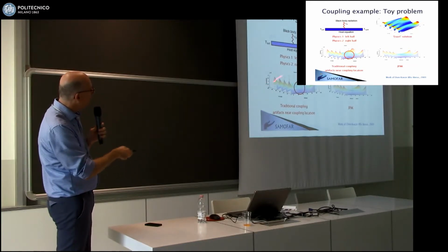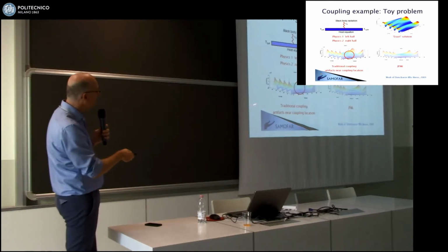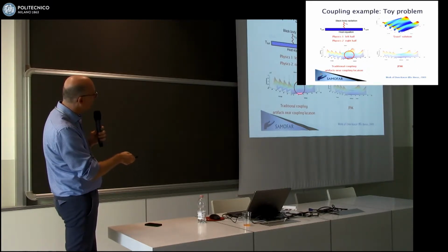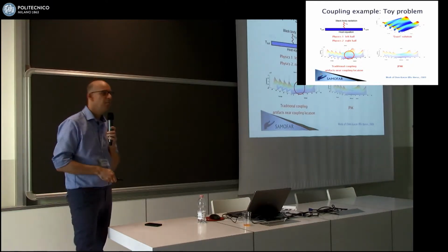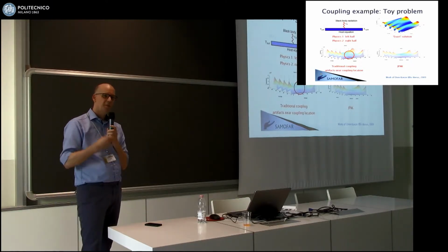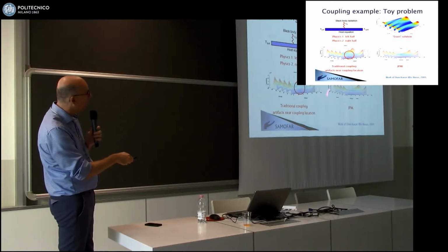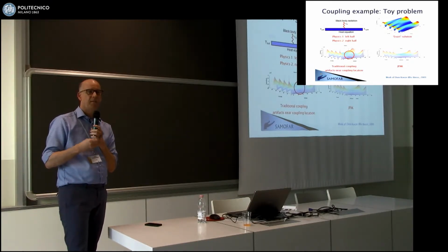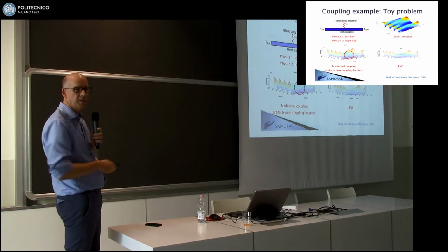And if you then do loose coupling on this problem, so the traditional method, then you get yourself a bit into trouble here where the physics get coupled. This doesn't really seem physical. This is the true solution, nicely smooth here, and loosely coupled for a rather big time step. It's a bit strange. So you get these artifacts with loose coupling. And this is then the Jacobian-free solution, which looks just fine. And so for large time steps, it really makes sense to have tight coupling and iterate out of the problem. Or you may have some of these artifacts.